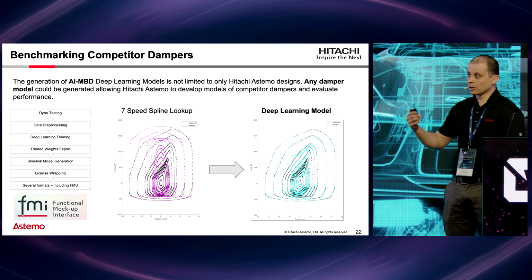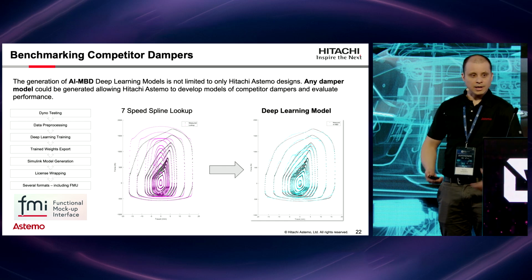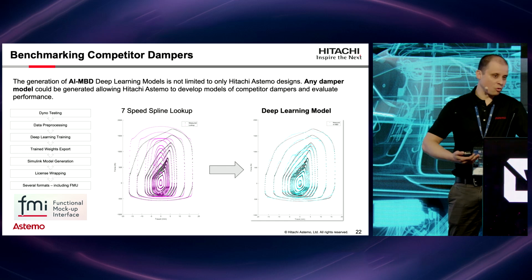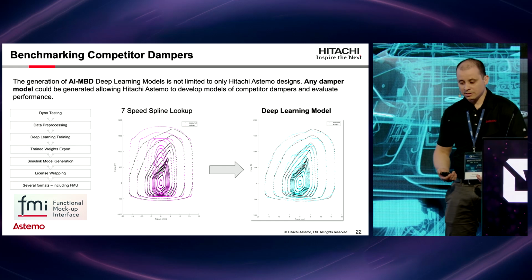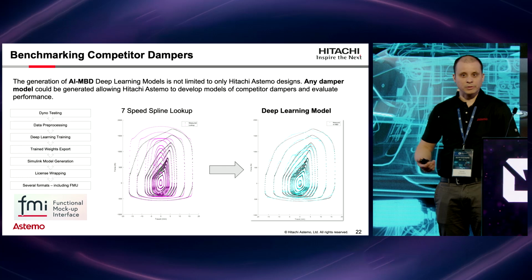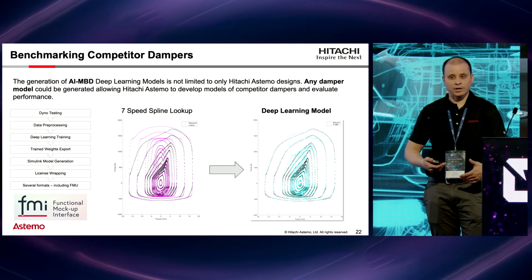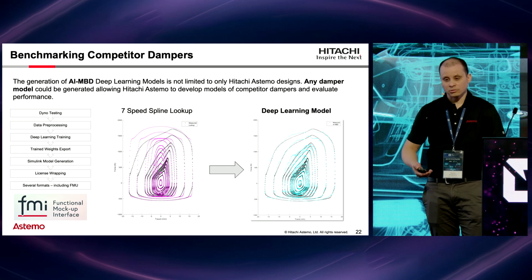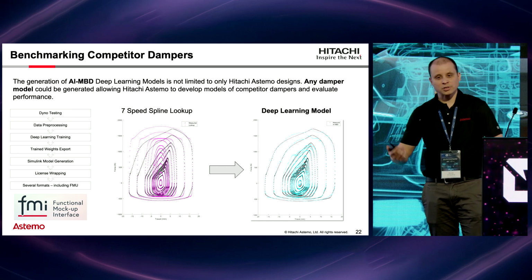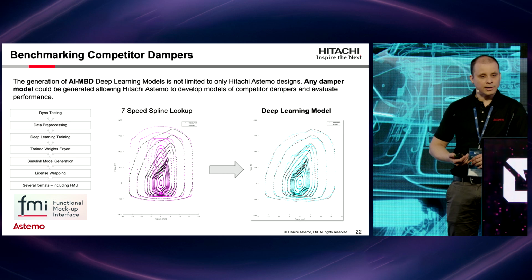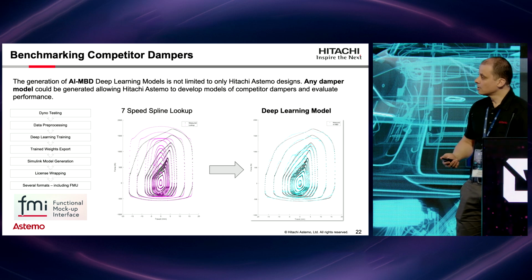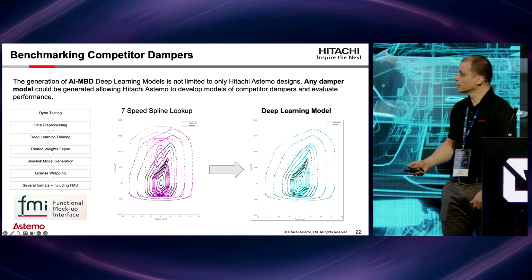For example, we can run at higher speeds, dampers more focused on just ride evaluations, ride and steering, or if you need durability, we now have the capability in our lab to run damper tests up to 6 or almost 8 meters per second, so we can generate these kinds of dampers.